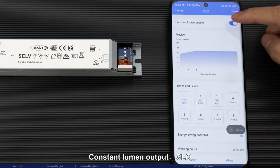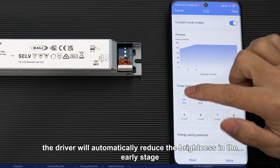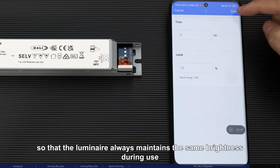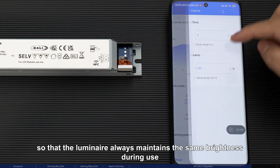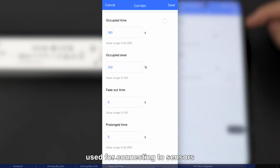Constant lumen output, CLO. With CLO turned on, the driver will automatically reduce the brightness in the early stage and increase the brightness in the later stage, so that the luminaire always maintains the same brightness during use. CD, corridor dim, is the corridor mode, used for connecting to sensors.